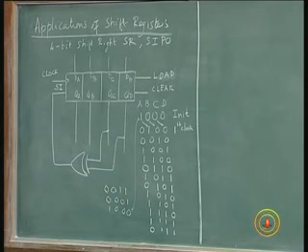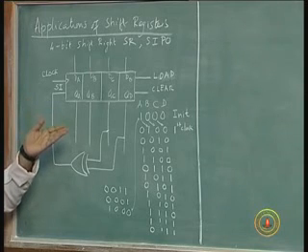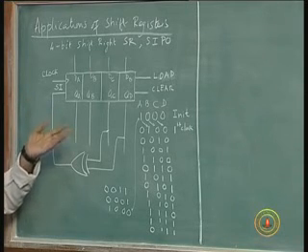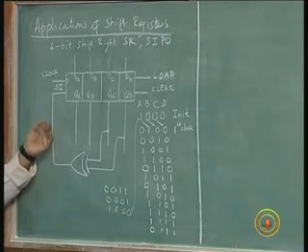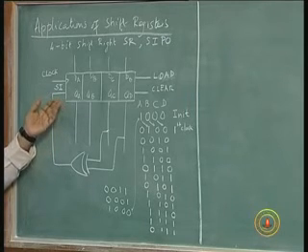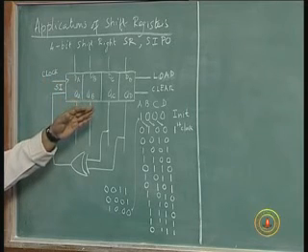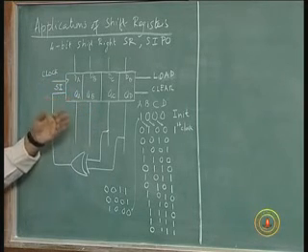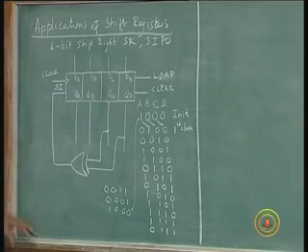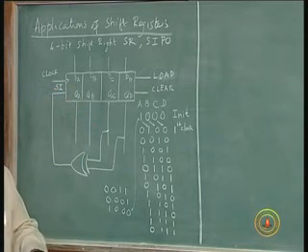So, by just putting in one initial pattern, of course this is only an arbitrary pattern, it doesn't have to be 1, 0, 0, 0. You can put any other pattern too. Every time you apply a clock pulse, the bits get shifted one bit position to the right, a new bit is added on the left, and then again shifted, and so forth. So how many different patterns are here?